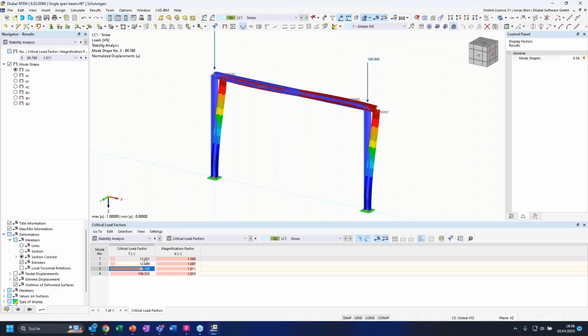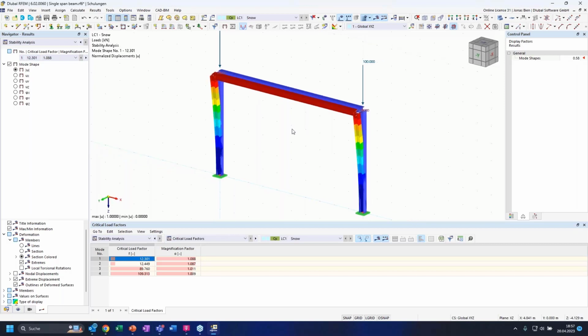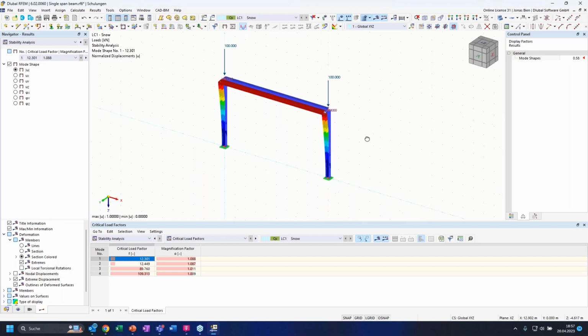But in real structures, you would probably not have such a separated or isolated frame, but this frame would somehow be restrained in y direction or braced in a structure. You could have another frame here and another frame, and somewhere it should be braced, or it should at least have some compressive links between those frames. So it usually cannot move out of plane like it does here.